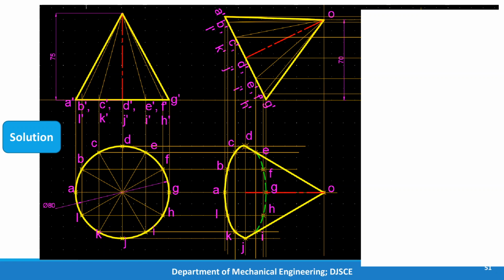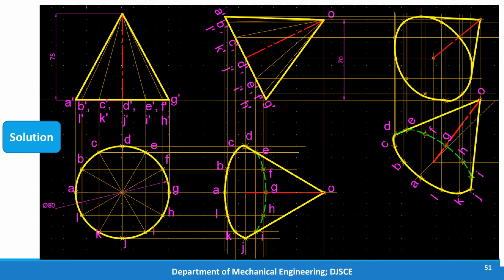And in the third step we have to reorient the top view of the second step such that axis making 45, it means that the true length of the axis, again we have to find out the apparent length using this concept. So the true length of the axis is here in this view. So mark this length at 45 degrees, get the locus, and then get this apparent length. This is the apparent length, and you can mark the apparent angle there and reorient this accordingly to that apparent angle. Take the projections and complete the front view of the last step.